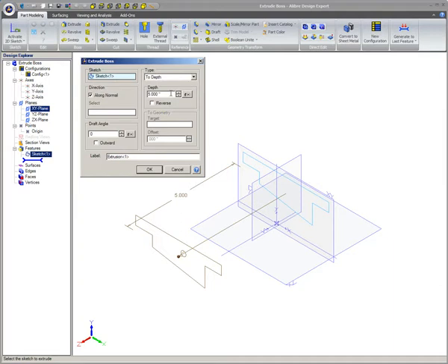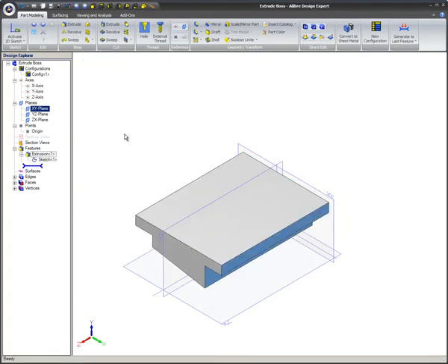When all the parameters are set in the dialog box, a preview of the resulting extrusion is shown in the workspace. Clicking on the OK button completes the extrusion. Notice the sketch was extruded in the positive direction along the Z-axis, that is, towards you, leaving the original sketch, the backside if you will, on the XY plane.